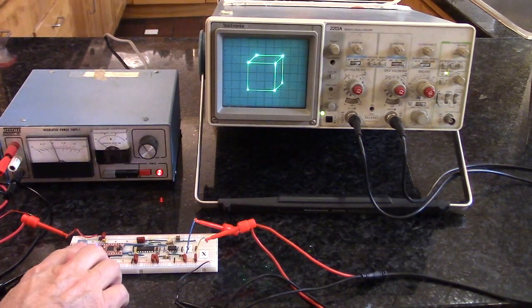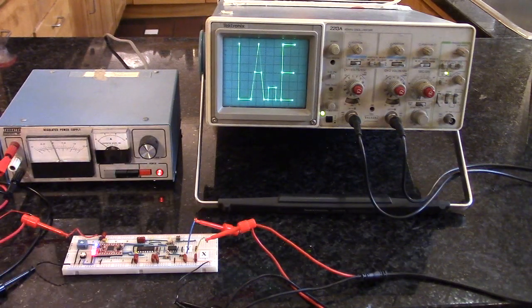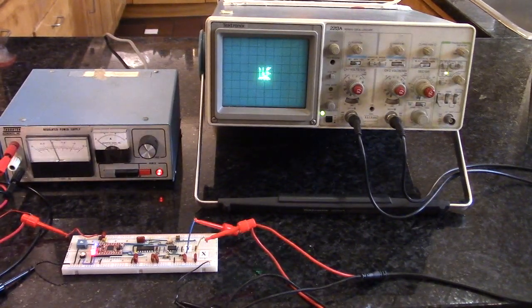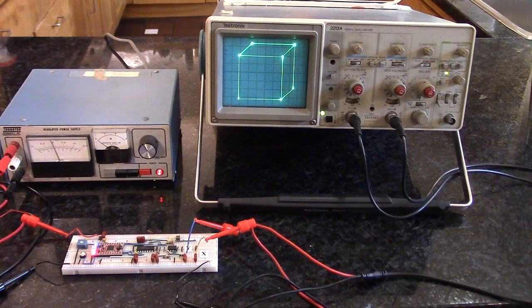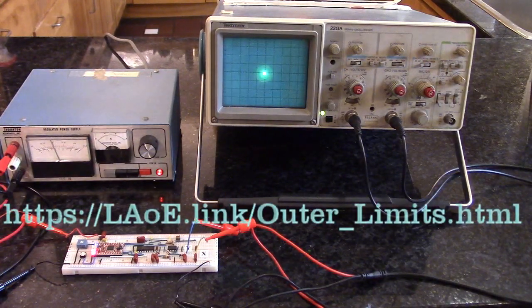And it doesn't really look a whole lot different with the static images, but you can see that now we grow from the center. As the reference increases, we change the offset so that it always keeps the 0 point in the center, and it's as though we had a bipolar DAC, which we don't. We have a unipolar DAC. Same thing with the cube. And this kind of looks more like what you expect a zoom to look like, particularly if you've ever watched old Outer Limits.